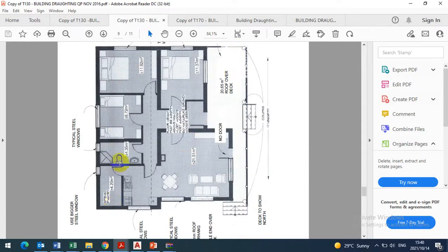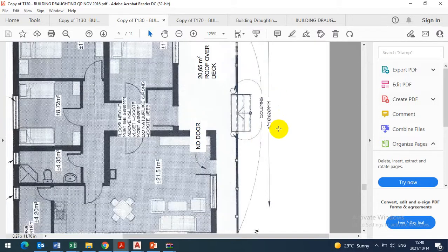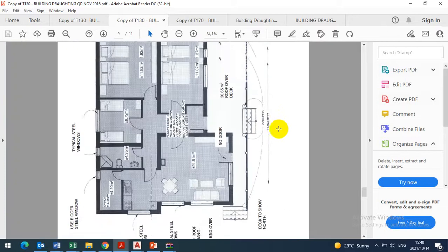The length for this room plus thickness 110, 220, 110, 220 plus the length must add up to plus minus 10,620. But be exact, because I've seen some memos for the examiner. He's coming to exact measurements. Don't play around with the tolerance. Just go exact for you to be accurate.